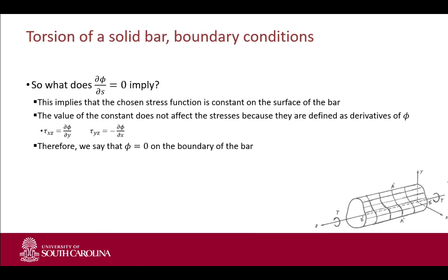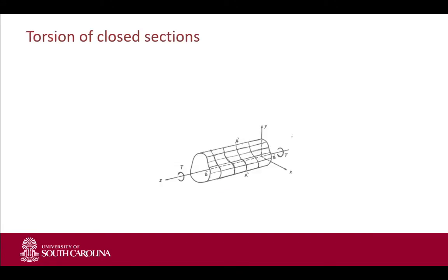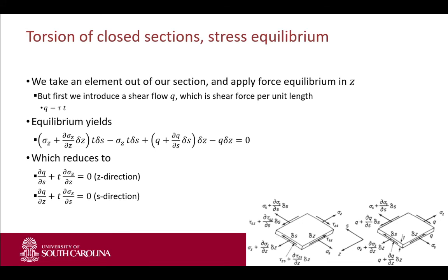So this is all thick walled. This is also thick walled. When we say closed sections, we automatically assume and imply that it's thin walled. Otherwise, it would be a solid. If we want to talk about torsion and closed sections or thin walled sections, that torsion will also imply shear flow. And once we know the shear flow due to the torsion, we can eventually come to shear stresses. And once we know shear stresses, we can state something about failure.